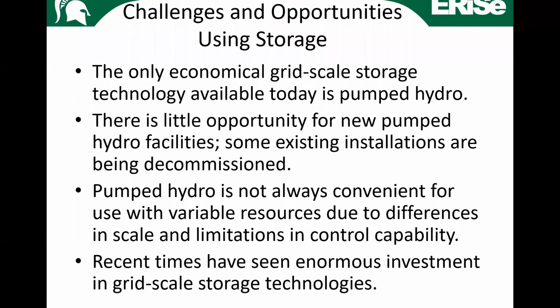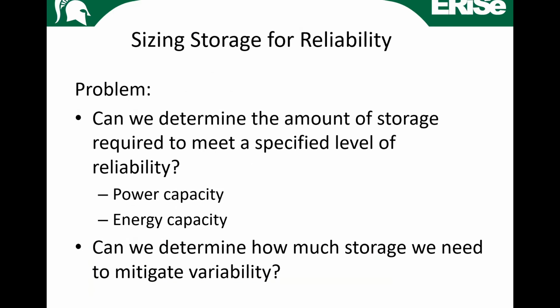Here are some challenges and opportunities using storage. Unfortunately, a lot of pumped hydro storage facilities are being decommissioned because of their age. Some are being rebuilt and renovated, but some are being decommissioned. And you need certain specific geographic features to build them, so you can't just go about building them everywhere. Okay. But as I was saying, recent times have seen enormous investment in grid scale storage technologies, and I'm hoping we'll see some demonstrations with these soon.